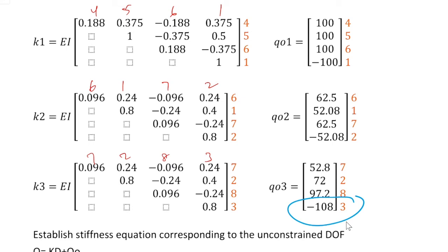We need to label the degree of freedom for each element. This is a very important step. You cannot skip it because this is the most important part of the analysis. We label according to the near and far end for each element: the first two for the near end and the last two for the far end. Inside each node there are 2 degrees of freedom, in Y and Z direction, because this is a frame. So we need to label YZ.